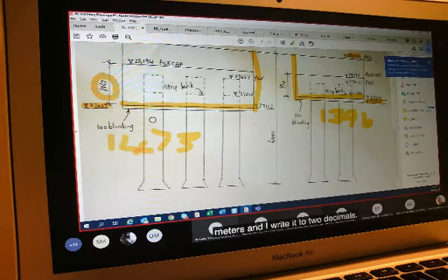1.07 is given to me as 1067. When I convert that to meters and write it to 2 decimals, it will be 1.07. And there's 4 of those piles. But I also have to deduct for this section here where the pile goes into my reinforced concrete. That will be 0.24 by 0.24, and I need to determine what that height is.